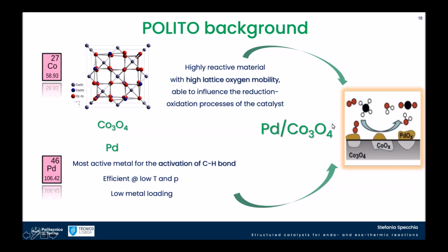We optimized this at powder level, by using small fixed bed reactors, this palladium oxide over cobalt spinel, where the cobalt spinel is very interesting because it has a very high lattice oxygen mobility, so it is able to provide oxygen to the palladium, which is very active towards methane combustion when it is in the form of palladium oxide.